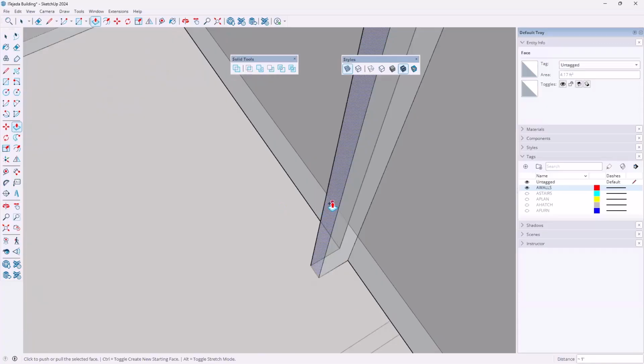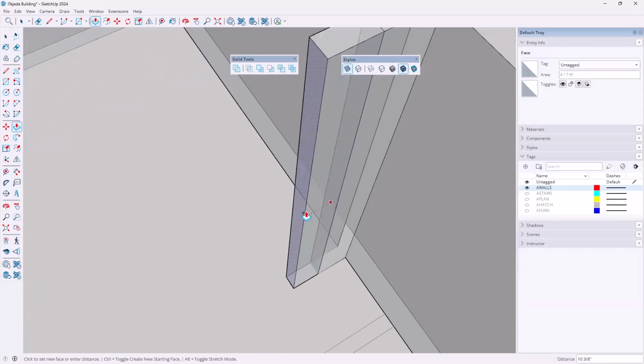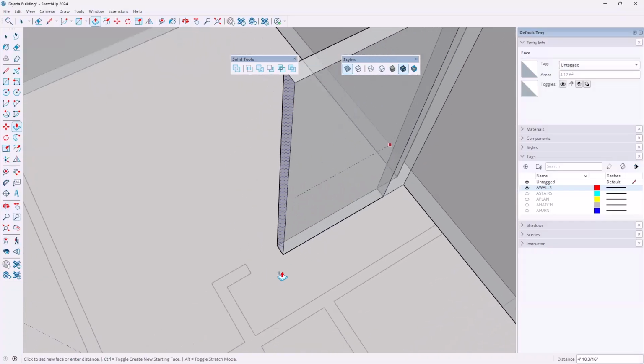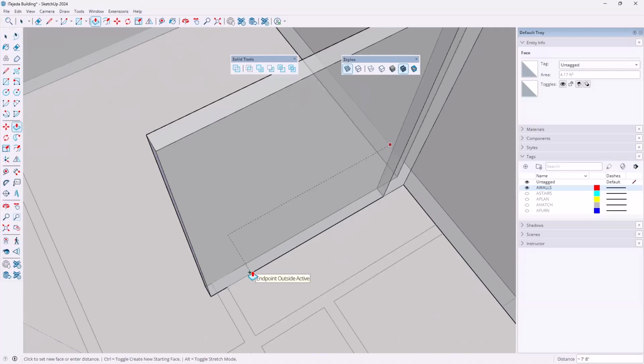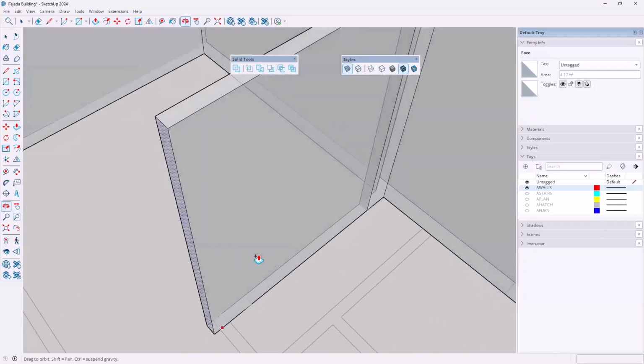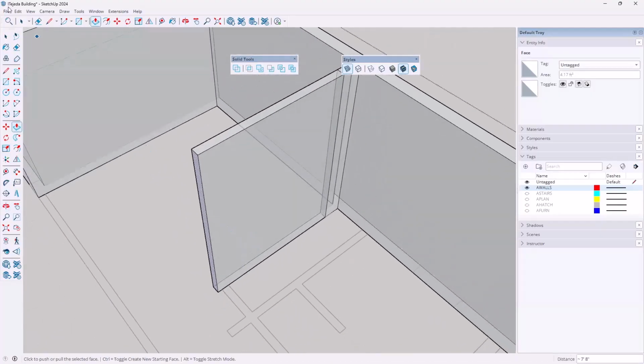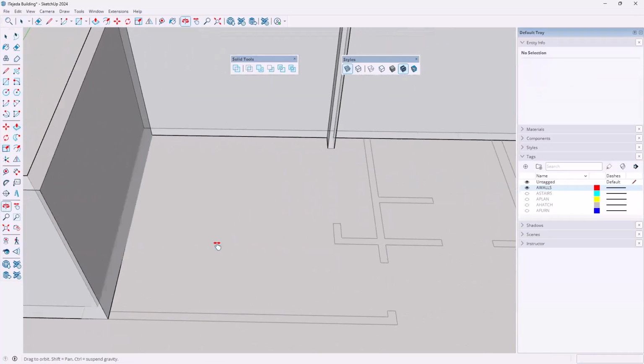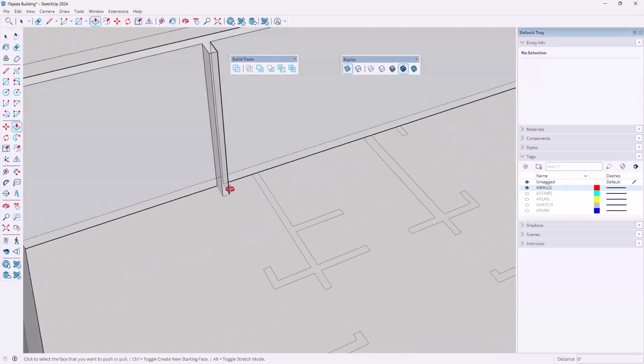So I'm going to make a copy from here. See how it's an extra or it's a new solid. And I want to take it all the way over to this endpoint. And it tells me it's going to lock into that endpoint, so I give it a click. And it actually went too far. I'm not sure why. So I'll just go ahead and edit, undo, and start over and maybe pick a different angle like this. So I'll go ahead and click on that surface, and I still have the plus sign on it. So I know it's going to make an extra solid.